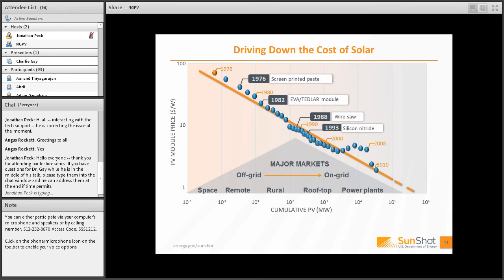The amazing properties of silicon nitride, in particular, not just for its anti-reflection properties, but for being able to hydrogenate multi-crystalline material, was discovered by folks at Kyocera. And Kyocera at the time had a joint venture working with Wacker that had pioneered not just the ability to scale making highly pure polysilicon as feedstock for growing single crystal, but had developed capabilities for casting of silicon.